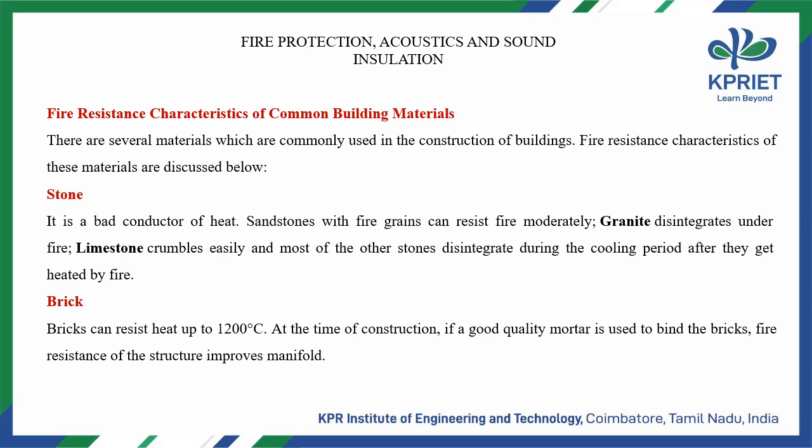Fire resistance characteristics of common building materials. There are several materials which are commonly used in the construction of buildings. Fire resistance characteristics of these materials are discussed below. Stone. It is a bad conductor of heat. Sandstones with fine grains can resist fire moderately, granite disintegrates under fire, limestone crumbles easily, and most of the other stones disintegrate during the cooling period after they get heated by fire.